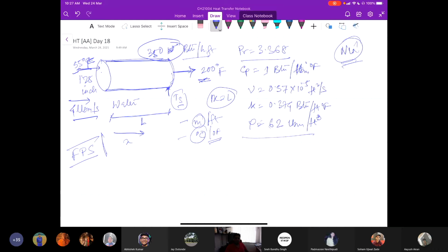So you have to deduce the velocity or superficial velocity. Pound mass per second has the equivalence in SI as kg per second. From there, you have to find out what is feet per second, and then you can use it in the Reynolds number calculation.